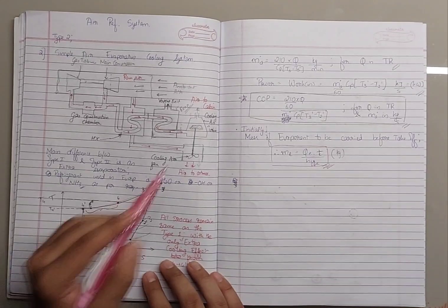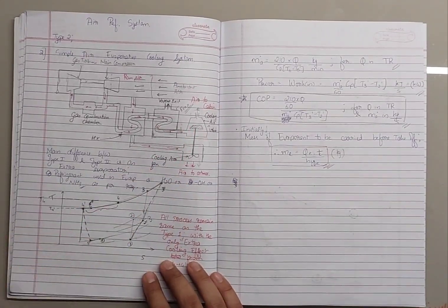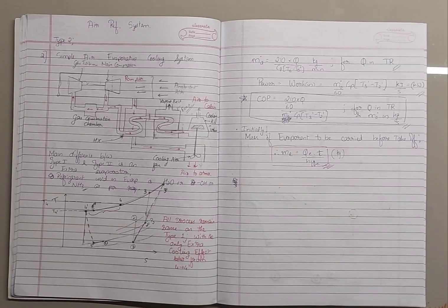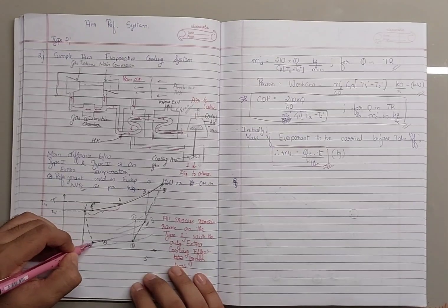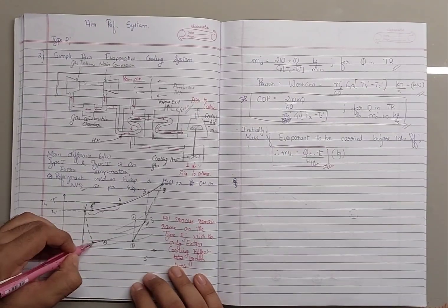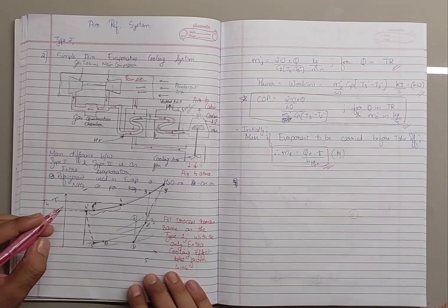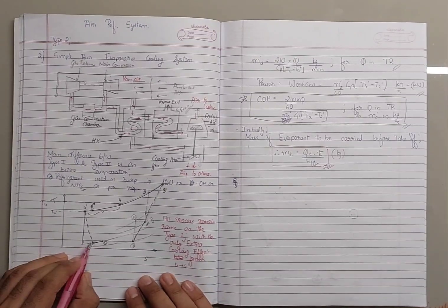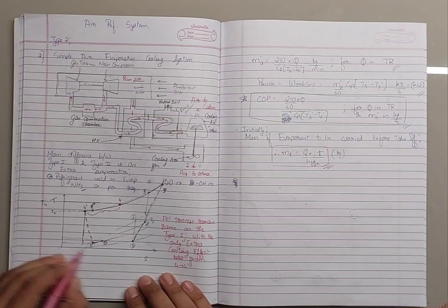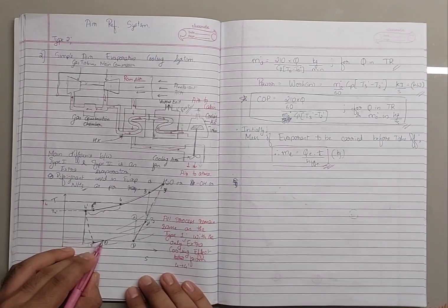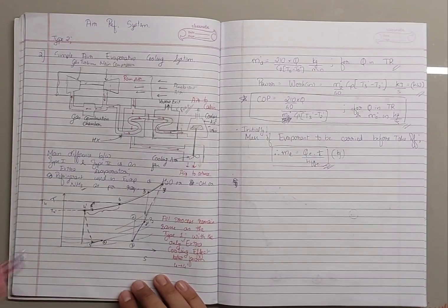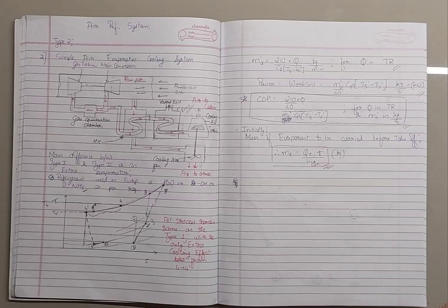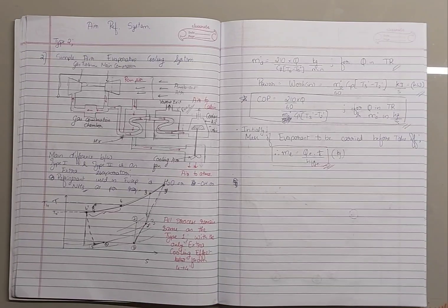So from 4 dash to 5 it reaches here, and after 5 there is an external apparatus which helps us regulate the temperature to be near the cabin temperature. Therefore we increased the temperature slightly. Rather, this point was better if talking about the refrigeration. From the coldness point of view, this temperature is lower than T6, but we went an extra mile to slightly heat it up to match the cabin temperature, to make sure that there is not much temperature difference between the refrigerated air passed to the cabin and the apparent temperature of the cabin.